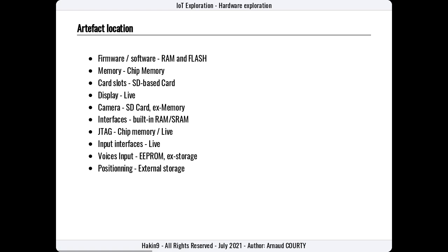You can note that some SD cards have an embedded write blocker. Remember to activate it even if you have a dedicated forensic copy device like Tableau hardware. On IoT devices, the display is an interesting sub-device because it is usually operated on I2C or SPI protocols. Understanding the pinning combination could allow you to access the bus directly and sniff the traffic.